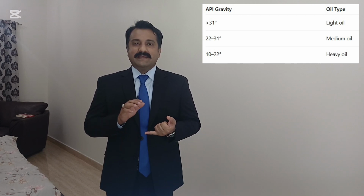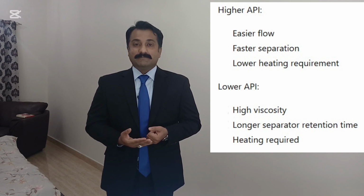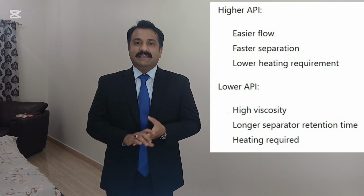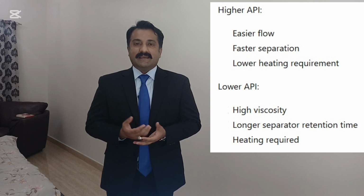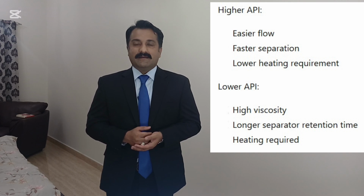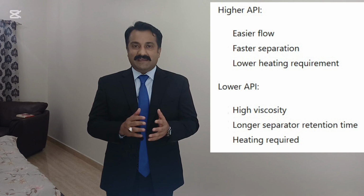If API gravity is higher, then the crude will separate easily. It can flow in pipeline or equipment very fast. It will require less energy to separate or for other processes. But if the API gravity is lower, then there is higher viscosity, it will require more heat for the other processes, and it will get higher retention time in the separator to segregate.